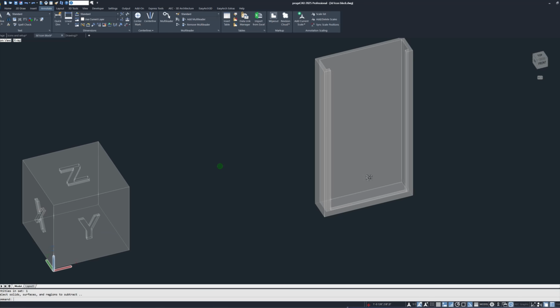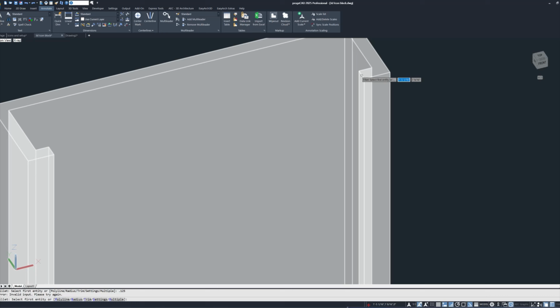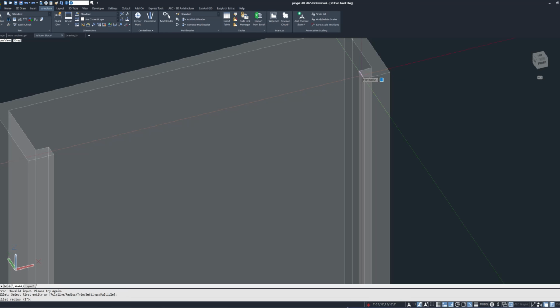There are many levels of a command called undo that will go back to the beginning if you like, so don't be afraid to experiment to get what you want. Spinning the objects is always the right thing to do to make sure you are on the right track. Notice there are some sharp edges on the corners that may cause some discomfort on skin or the phone, so let's look at a command called fillet.